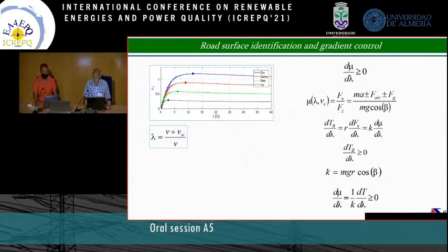This is why many traditional methods exist to estimate the friction depending on the slip. In our case, we try to replace friction with real torque under the tire and try to find the ratio between torque and slip, and to provide control using this ratio instead of a system which can understand the surface under the tire. This is the approach which we call the gradient torque approach.